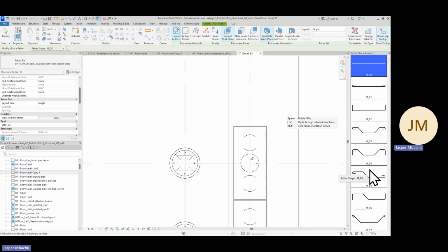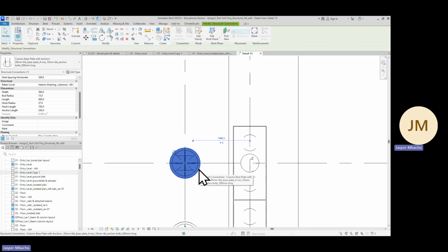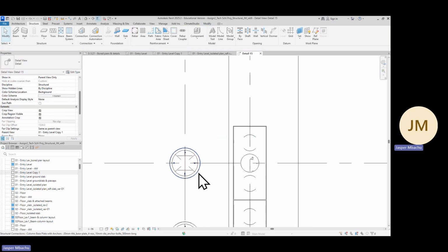You know the rebar cover that we did, instead of selecting each individually, you can select all of them at once, and then at the rebar cover panel, select 50-50-50 across all those settings. This is quite good. Thanks, Olivia, for that.